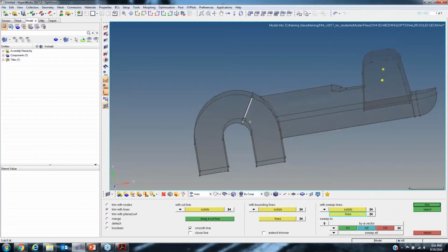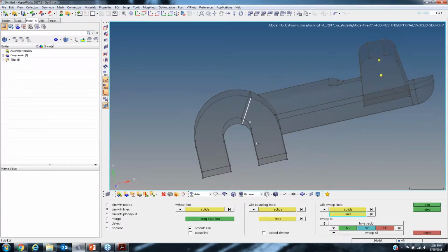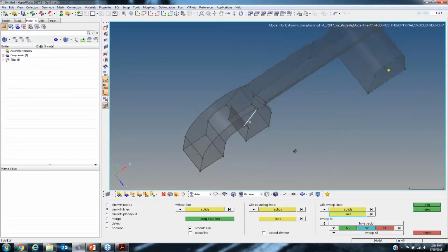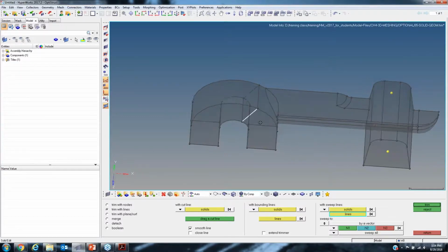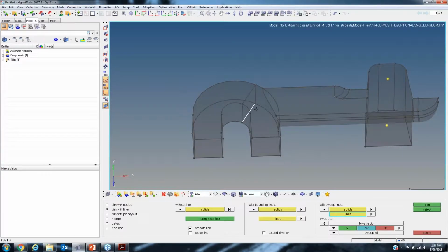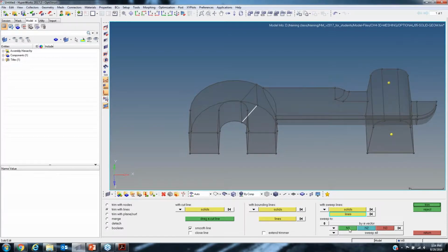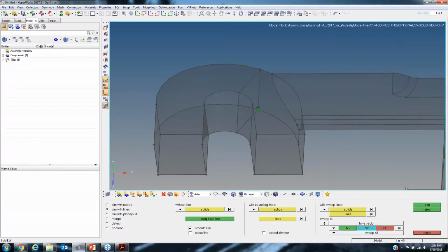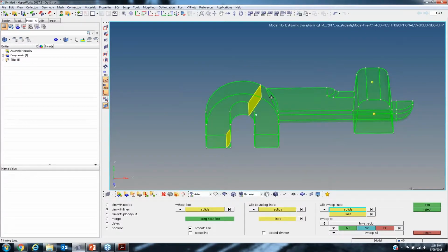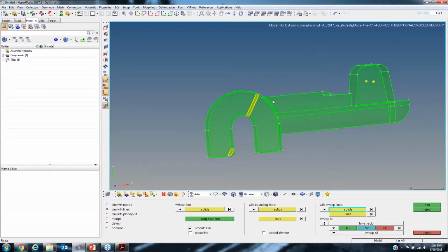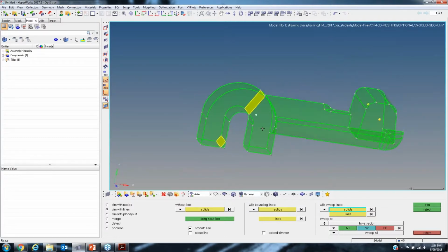So I want to use that line to cut through the thickness of this, right? So then I need to specify a direction. Which way do I want to cut this, right? This is going back to what I showed you guys at the beginning, and this is why I put so much emphasis on it, because you use this a lot. If you want to cut through this thickness, you can select either N1 or N2, right? So we can just click here, and that'll specify a vector in that direction. I can click trim, and you'll see that it used that line to infinitely cut through this geometry.